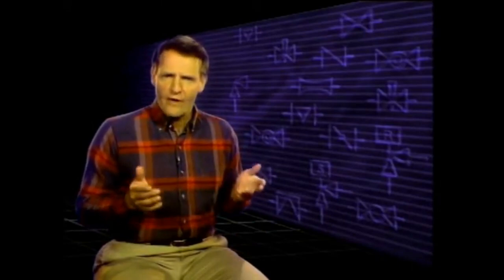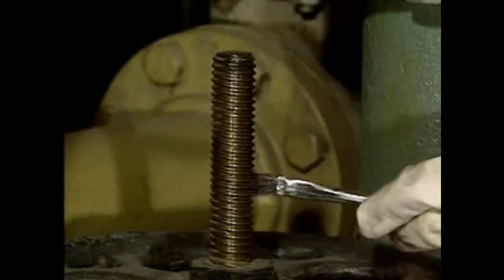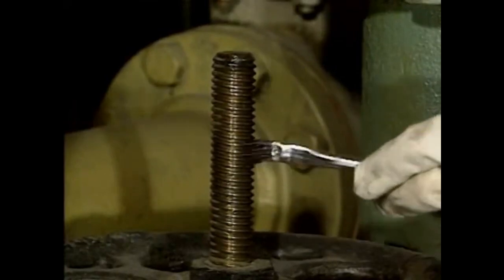Besides locating and identifying leaks, another task that an operator may have to perform is valve lubrication. Valves need lubrication to prevent components from wearing during operation. Each type of valve may require a different type of lubricant or method to apply the lubricant. For example, some valves have grease fittings and require the use of a grease gun to lubricate them, while other valves may have the lubricant applied directly to a component, such as this valve stem.